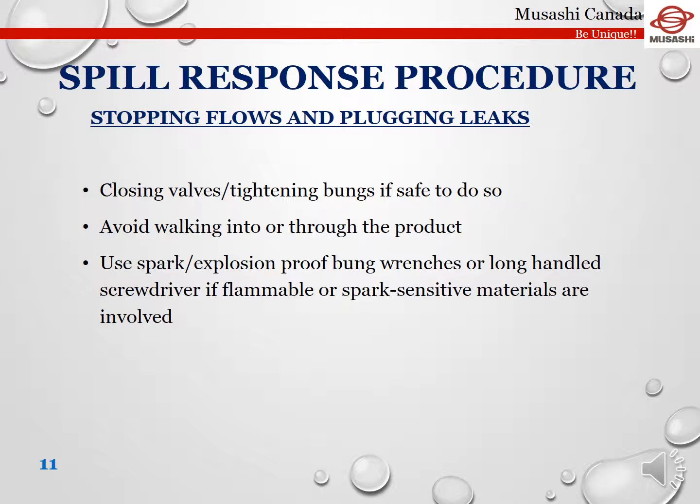Spill response procedure. Stopping flows and plugging leaks. Closing valves, tightening bungs if safe to do so. Avoid walking into or through the product. Use spark explosion-proof bung wrenches or long-handled screwdriver if flammable or spark-sensitive materials are involved.